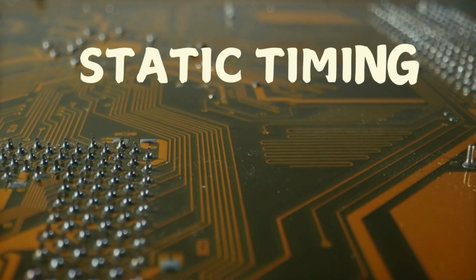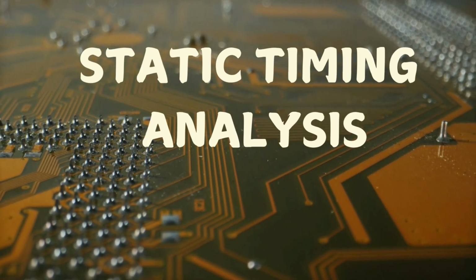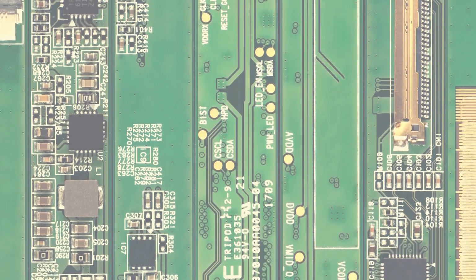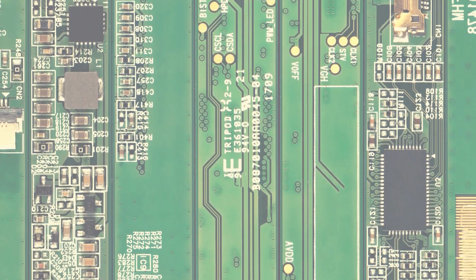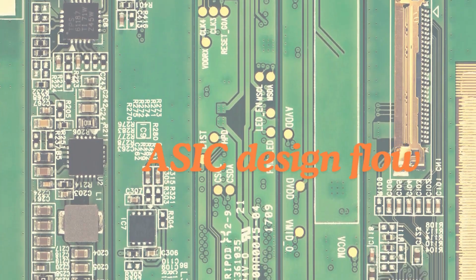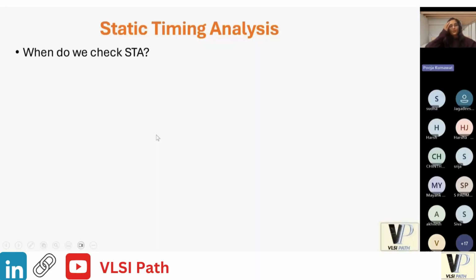This is part of our static timing analysis series, guiding you from basics to advanced concepts step by step. Today we are going to discuss the stages of STA in the ASIC design flow. So let's dive in. When do we check the STA? As I said, it won't be performed only on a single stage. We start very early in the design, and the checks become more accurate as we go lower in the VLSI design flow.